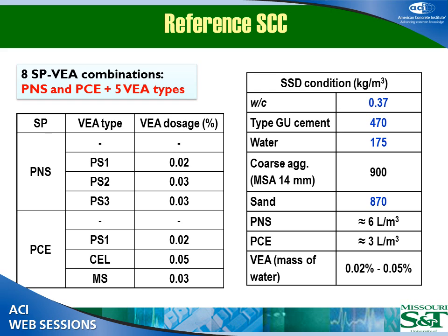Okay, we selected one mix design, and this is a mix design that is targeted really for precast applications. So precast applications, it could be structural applications, or it could be architectural types of applications. Like I said, the mix itself is very stable. It has quite a bit of cement, low water cement ratio, and aggregates are optimized, grading, etc. We are using very low dosages of VMAs to promote robustness.